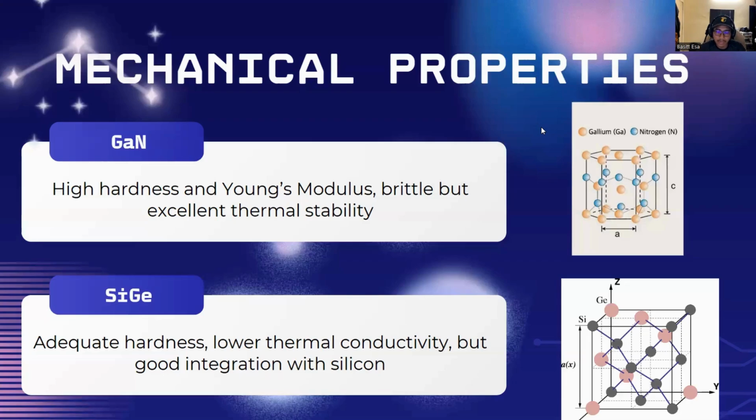However, it becomes challenging to manage defects, such as misfit dislocations, because of a lattice mismatch between silicon and germanium. These defects can be controlled by the precise control of the germanium content and epitaxial growth conditions. Advanced epitaxial techniques leading to the buildup of single crystal silicon germanium layers minimize grain boundaries in these layers, resulting in improved mechanical and electronic properties.